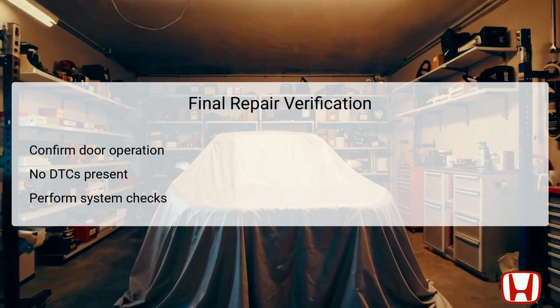After completing the necessary repairs, it's essential to verify the functionality of the sliding door system by confirming that the door operates without issues. This verification step is critical, as it guarantees that the components are working harmoniously and that the DTC B2028 does not return. By running a comprehensive system check using the Honda Diagnostics System, HDS, the technician can monitor for any new or lingering error codes that may indicate unresolved issues. This ensures that all aspects of the system are thoroughly addressed before closing the job.